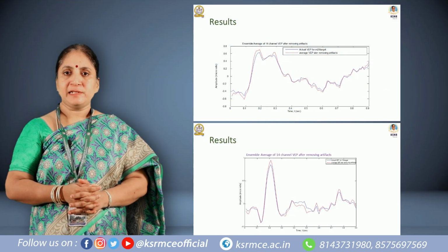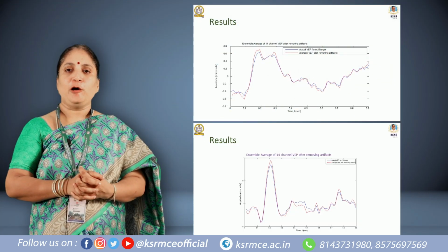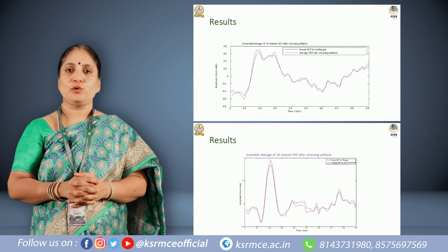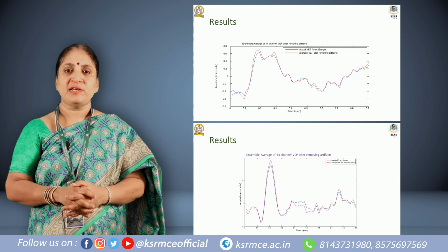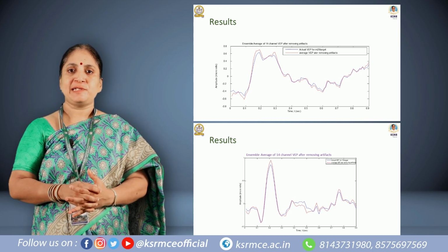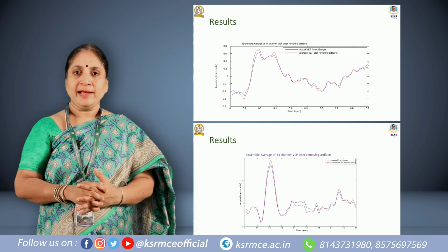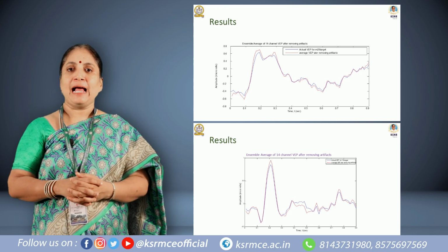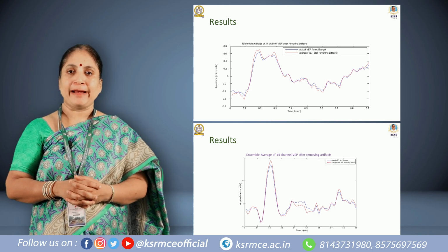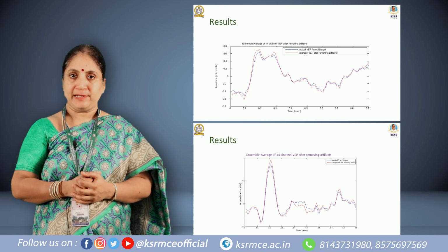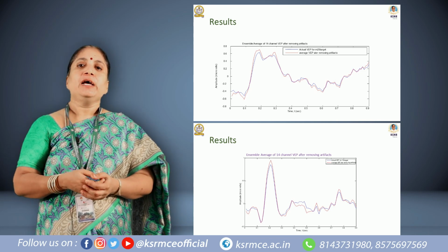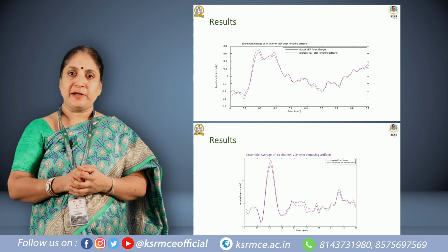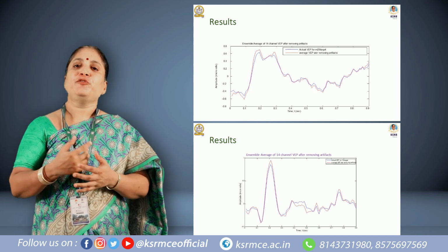By applying these various methods to identify the artifacts, that is ensemble averaging, clip test, standard deviation test, kurtosis test, correlation test, and mode deviation test, we can identify the artifacts. By removing the artifacts and considering the ensemble averaging of all the channels and all the trials, the result is plotted as shown in the figure. Here in the figure we can observe two waveforms: one without removing the artifacts, and the other with the artifacts removed.